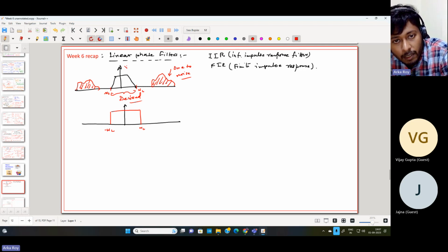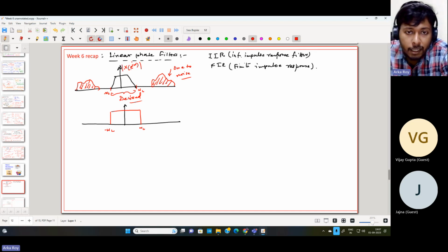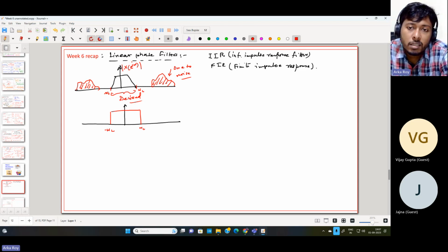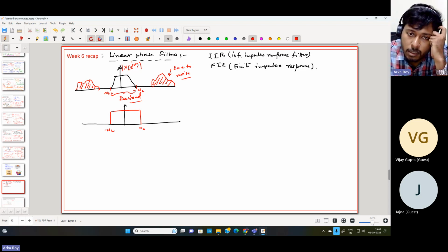So this is effectively your Xc(j omega), and I'm taking the magnitude. Any complex number, as this DTFT is basically a complex number, as we can see that we are having some complex exponents, so cos theta plus j sin theta, it will give rise to a complex component. A complex component will have two parts: one is the magnitude part and one is the phase part. So I'm drawing the magnitude part over here only.